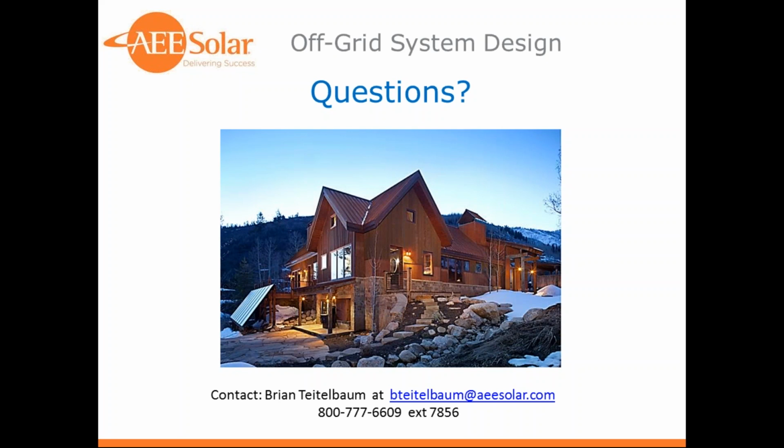And then that can be an issue if you have, say, 8 feet of snow cover. I would recommend in that situation to mount at least some of the PV at a 90-degree angle, like on a wall. It's obviously not optimal for energy production, but it's less likely to build up snow in front of it, and at least you'll get some charge on the battery at that point in time. But yeah, cabins that are used periodically, might be a weekend use and you have all week to charge up, you could probably use a smaller PV array and even a smaller battery. You're just going to have to factor those things in when you're doing your system design.